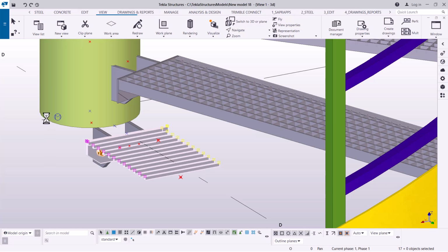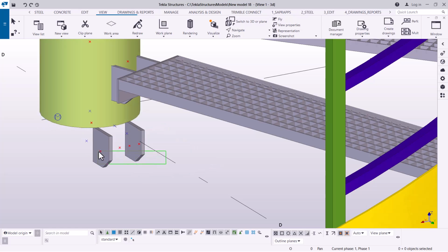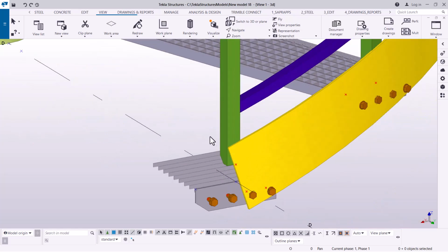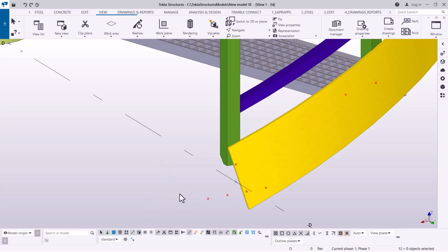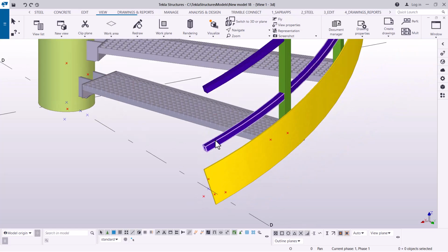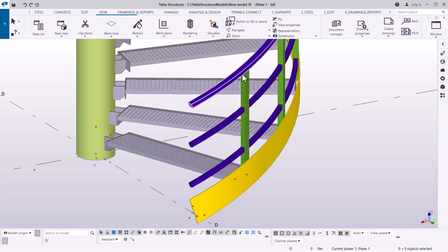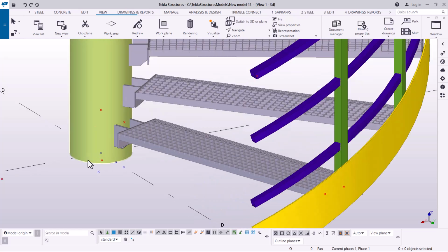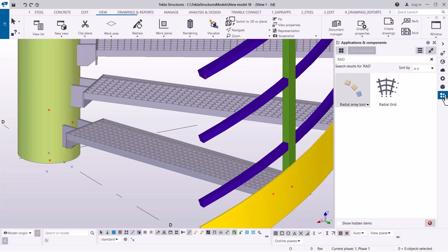because the reason why I'm deleting this, because at the bottom end here we'll place a base plate. So when you place the base plate, that thread will be hitting, will even sink on the ground. So it won't make sense at all. So even this handrail, we'll just have to get rid of it. So you find the handrail and the post, you have to get rid of them. Now at the bottom end here, what you are going to do is to bring in a base plate. So let's handle the base plate as a different topic.